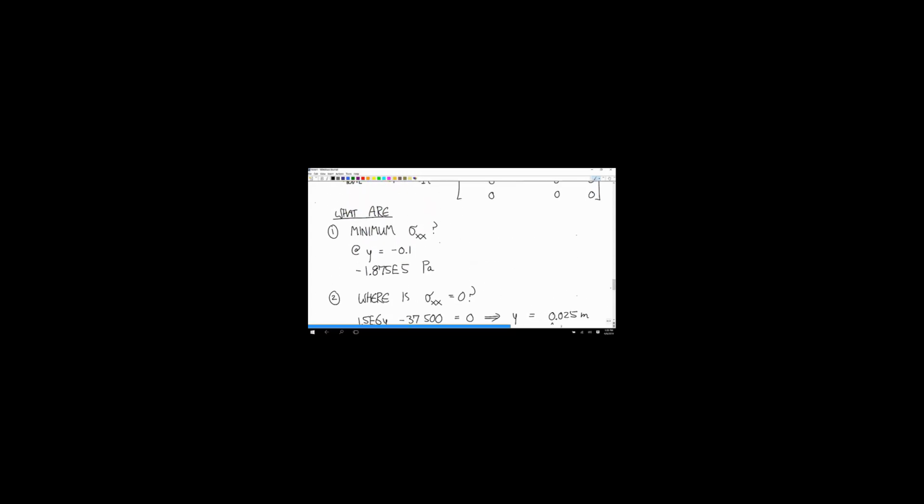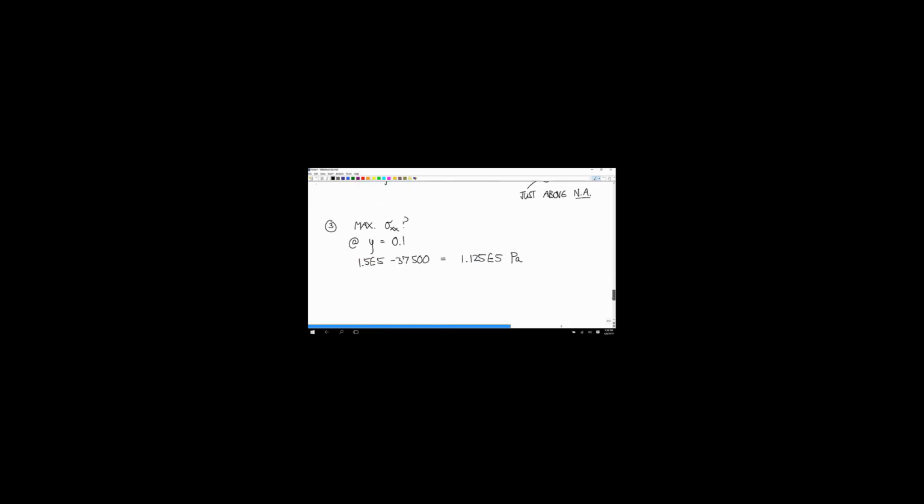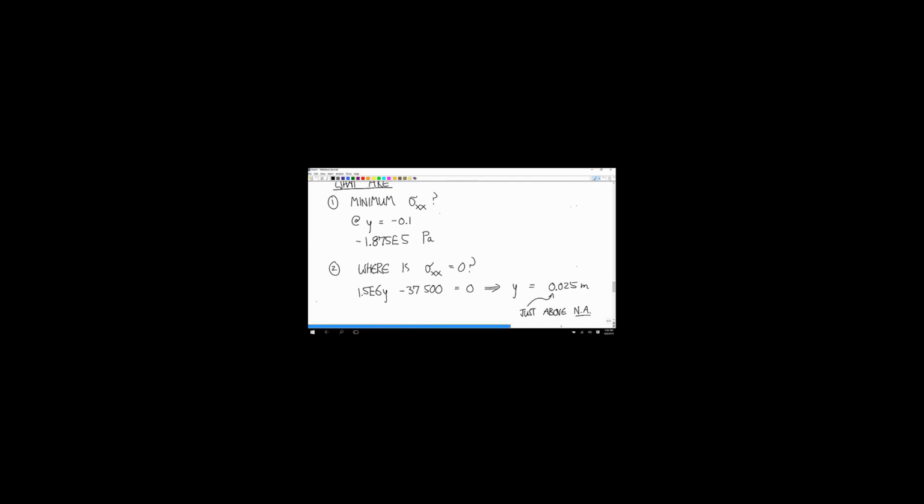So there are a lot of cases where there's a natural symmetry that comes from the bending moments, depending on how much above or below the neutral axis you are. The tension compression messes that up when you add the two together, because the tension compression doesn't change as you go up and down. And so that's why in this case we have a bigger absolute value at the minimum than we do at the maximum. And that's something you can take advantage of in some engineering environments.